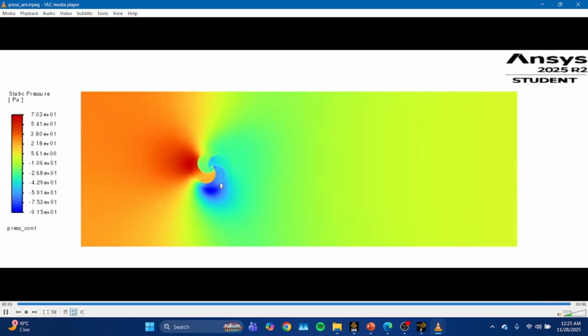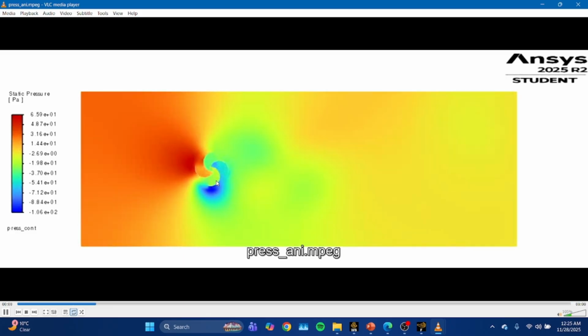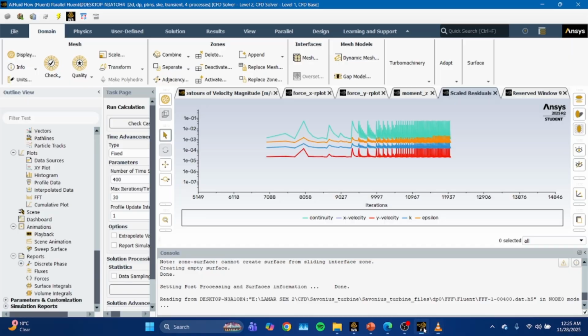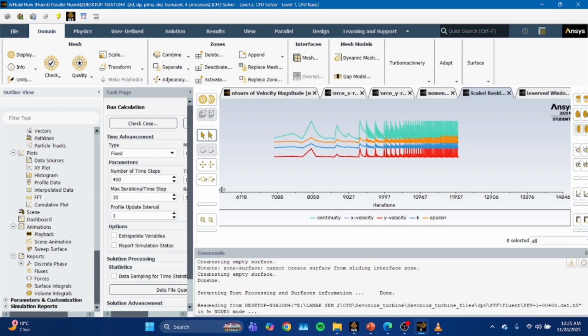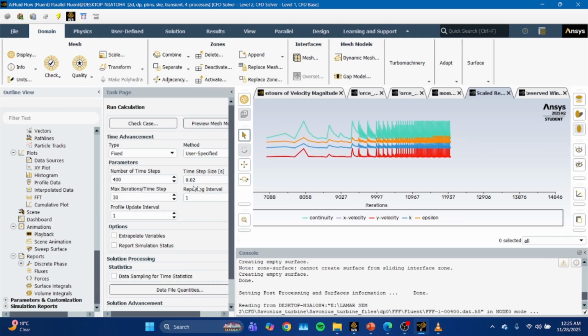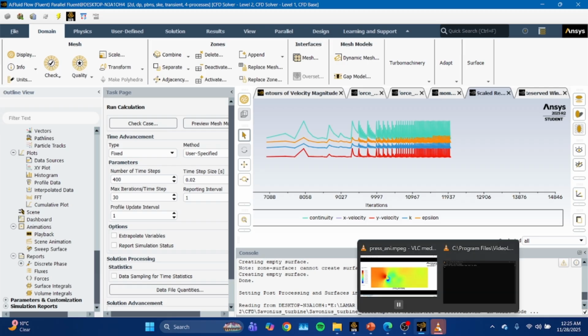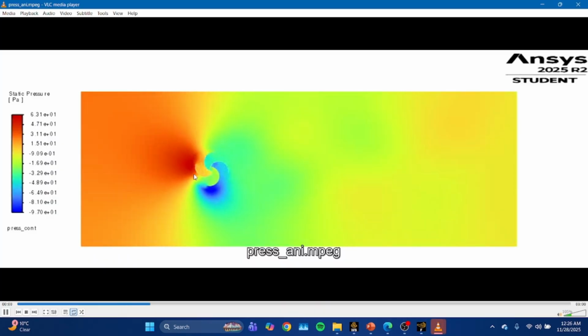To slow it down to more time steps, we can reduce the step interval that we have selected earlier, 0.5, to 0.25 or 0.2, I guess. So we can reduce the time step more, so our simulation will be shown in more slow motion.